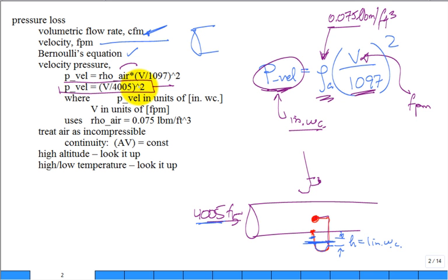A lot of residential duct systems, you don't want to go over 1,000 feet per minute because of what you can hear. You can sometimes hear air rushing through ductwork. If we're real quiet taking an exam in some classrooms around here, you can hear it, right? If in my office I'm quiet, I can hear it. I can hear maybe the fan and the computer running, the fan up at the projector running, but it's unwanted noise. Anybody been in a house and they really are annoyed by that? The air conditioning system's running, they're trying to sleep? Yeah. And so I've learned a lot of times that you keep it low, you keep it at 1,000.